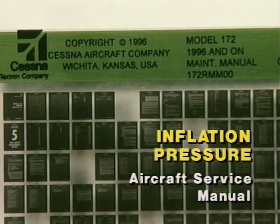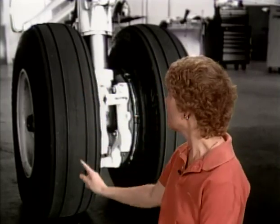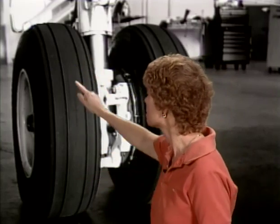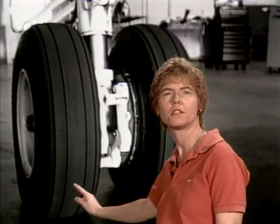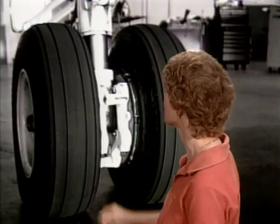Now, when you're looking at tires, you can tell whether a tire is overinflated, has been overinflated, or underinflated. An overinflated tire is going to tend to cause excessive wear right in the center of the tread. And the reason for that is too much pressure. It's basically just the very center part of the tread that's going to be in contact with the ground, so you're going to get excessive wear in the center of the tread. Another thing that it can cause is damage to the wheel flange. The excessive pressure here can actually cause damage to the wheel flange.